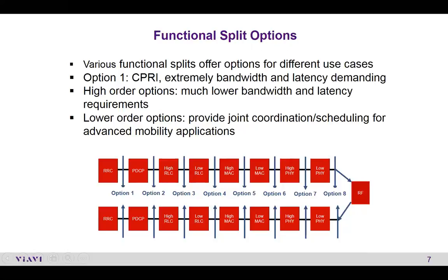We can coordinate all these radios over this interface, which is CPRI, basically option 8. We can centralize, pool these resources. So that's why CRAN is so successful, because we can do all that. However, the problem is this interface is very bandwidth intensive.